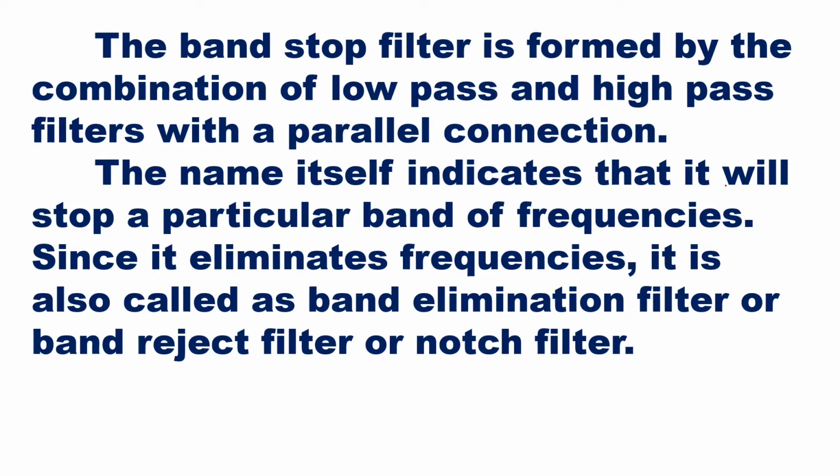So if you see the description, the band stop filter is formed by the combination of low pass and high pass filters with a parallel connection. The name itself indicates that it will stop a particular band of frequencies. It is working as the opposite of a band pass filter. Since it eliminates frequencies, it is also called a band elimination filter or band reject filter, or notch filter if the band of frequency which you are rejecting is very narrow.